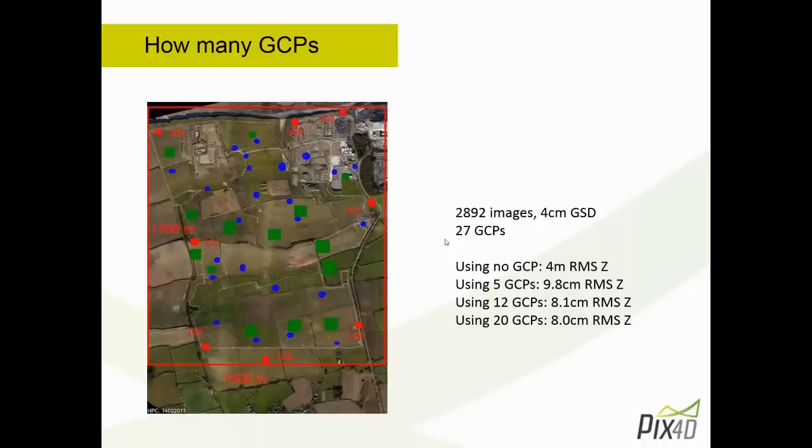So without any ground control points, indeed, you get something like a 4 meter inaccuracy in that direction, by looking at all the control points on the field. This basically is the error introduced by the geotag, the inaccurate GPS on the UAV. However, by using 5 ground control points, only 5, the error on the 22 other GCP stations was 10 centimeters. Sorry, GSD means ground sampling distance, the size of a pixel on the ground. So each pixel is 4 centimeters on the ground.